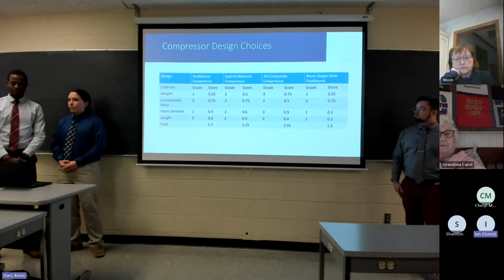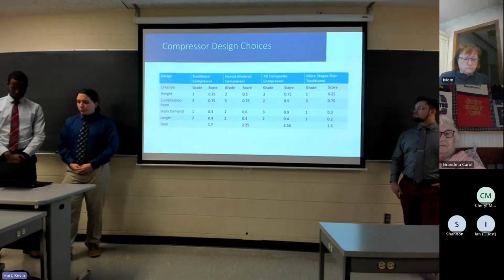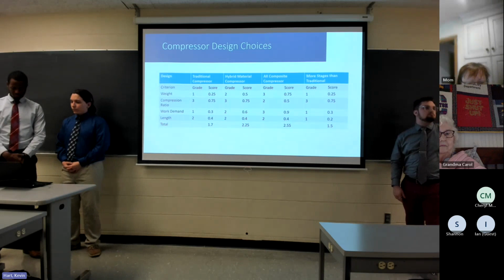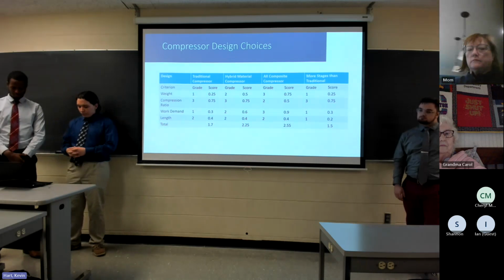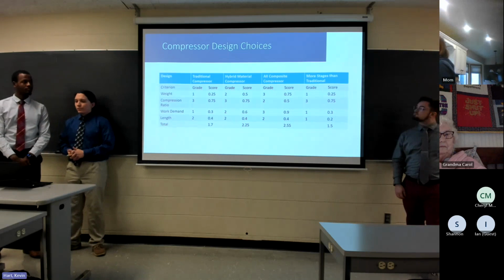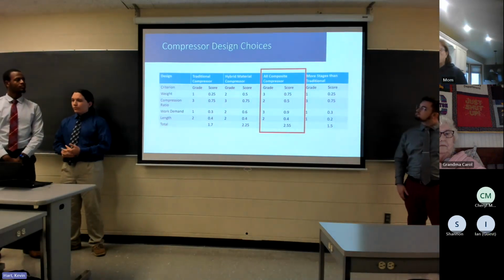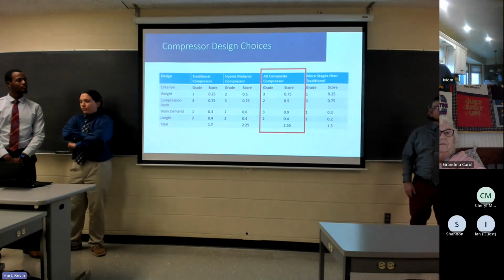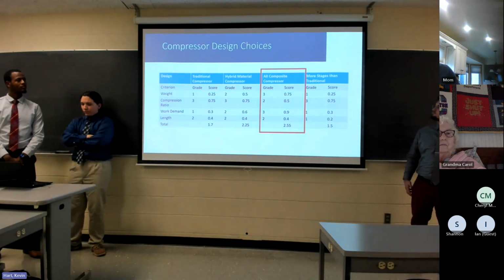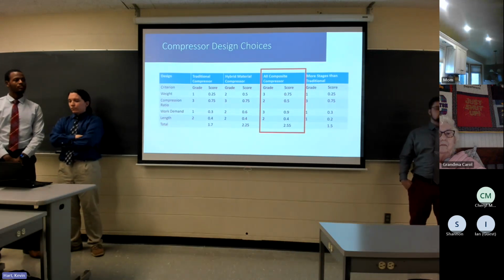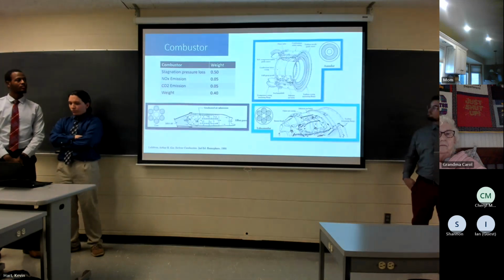And this would be beneficial, since it's before the combustor, high temperatures are not too big of an issue, and so material constraints aren't anywhere near as severe as later in the engine. Then we looked into a little side study. So that's what we were able to come up with for our design, but then also adding more stages than traditional, which would add more length, would allow for less work demand, and overall, we came up with the all composite compressor.